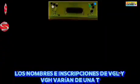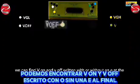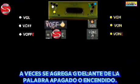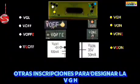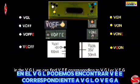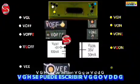The names and inscriptions of VGL and VGH vary from one TCON board to another. We can find V on and V off written with or without an E at the end. Sometimes a G is added in front of the word off or on, G corresponding to the first letter of the word gate. Other inscriptions to designate the VGH and the VGL: we can find VEE, corresponding to VGL or VEEG. VGH can be written VGG or VDDG.